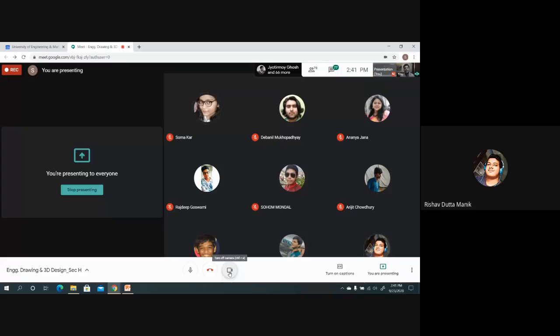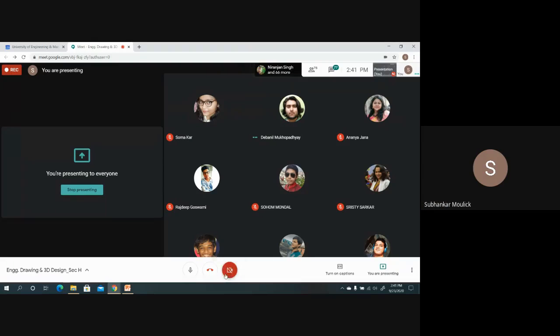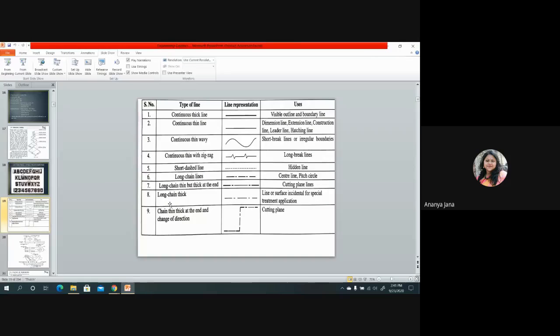Similarly, if you are observing any drawing from the top side, definitely the bottom side will not be visible to you, but the bottom side is present. The extreme two, left hand side and right hand side, will not be visible to you, but left hand side and right hand side are present in the drawing. For that we use dash lines. I hope it is clear. Yes, sir. Fine?